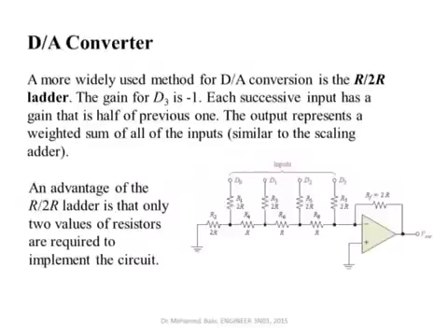Okay, so in lecture 12, we saw how to build an analog to digital converter. For 3 bits, we used 8 op-amps to compare against 8 different voltage levels, and then we were able to create a binary output. The circuit I'm showing you here is a digital to analog converter. What you do is apply a digital word here. We have 4 bits, D0, D1, D2, and D3.